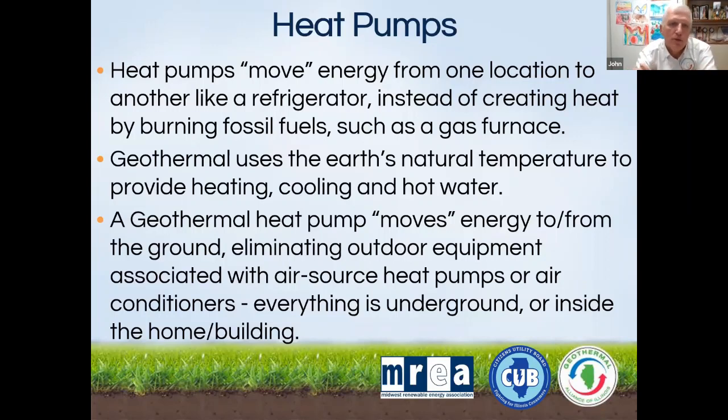Geothermal is much like an air source heat pump in that you just move energy from one location to another, much like a refrigerator takes heat out of the inside of the refrigerator and sends the heat to the exterior, much like an air conditioner takes the heat and humidity from your home and puts it into the air. Geothermal does the same thing, except in air conditioning mode it exchanges the heat down into the Earth's natural temperature, and in heating mode in the winter, it takes heat out of the ground.